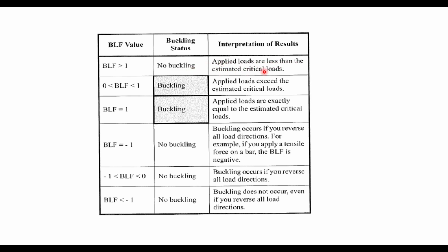So if the buckling load factor is greater than 1, your model is satisfying the buckling conditions. If it is between 0 and 1, then definitely your component will buckle, as it exceeds the critical load. If it is equal to 1, the critical load and the applied load are the same, so it is definitely going to buckle. Remember that.